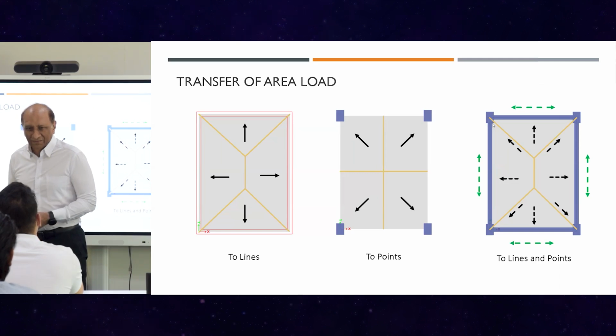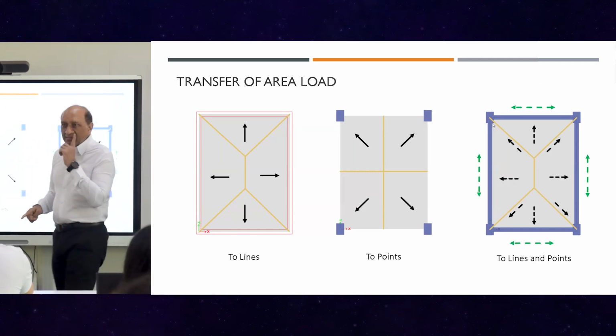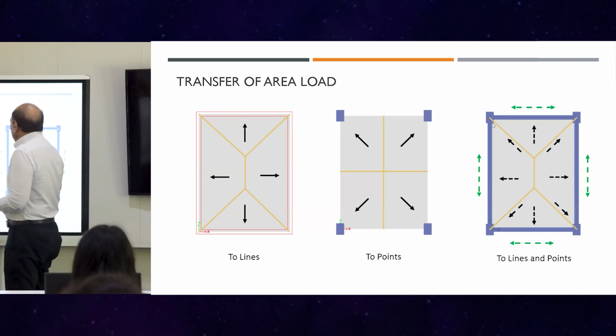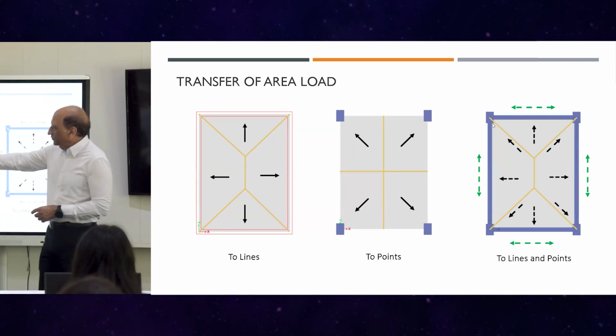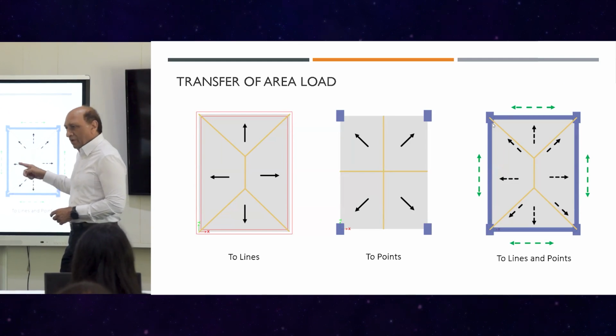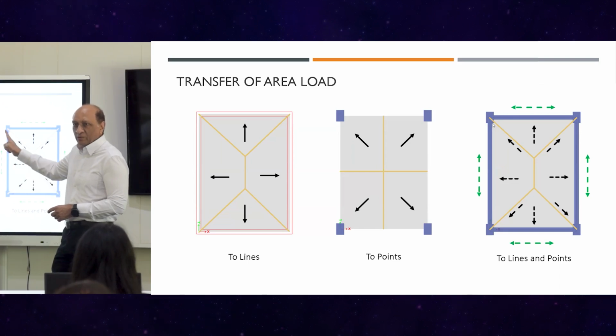Yes. Depends on the stiffness. Correct. So now let's see, depends on the stiffness of what? Slab and beams. Correct. Slab and beam stiffness will decide which path will exist, or how much percentage goes straight, how much percentage goes through the beam back to the column.